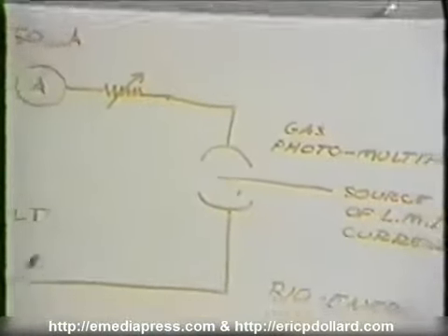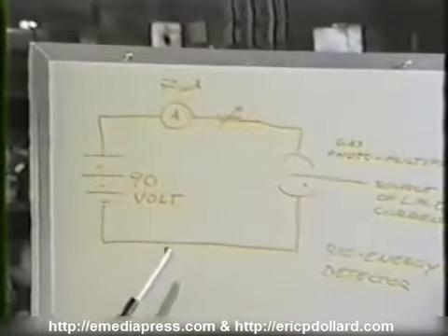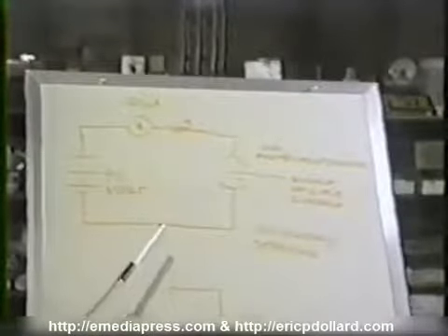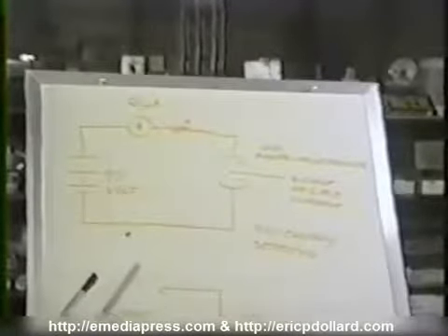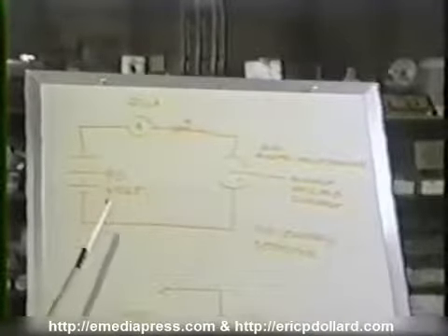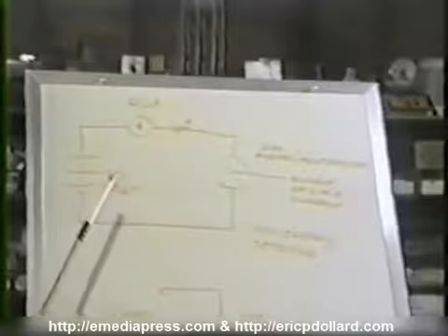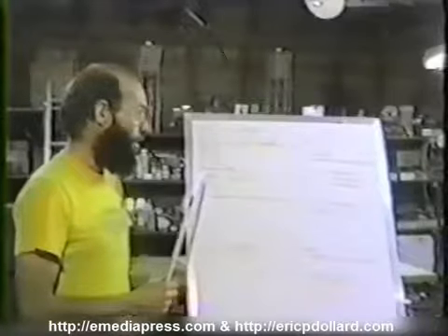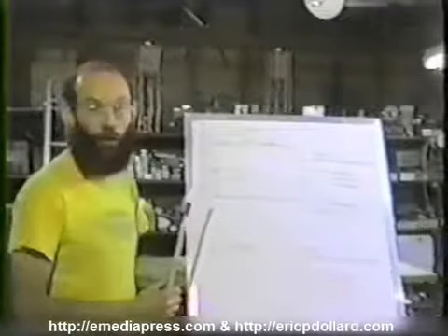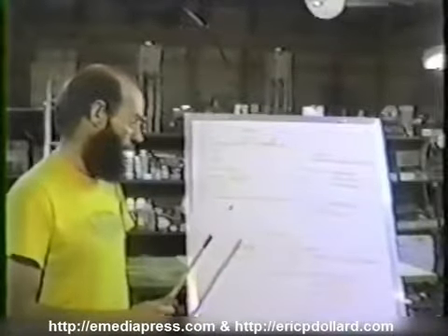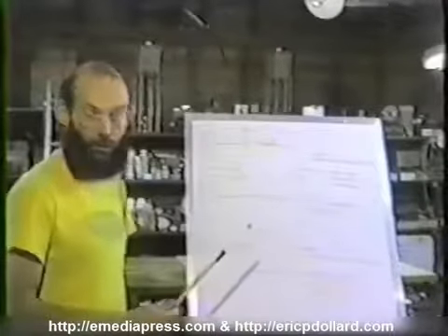The reason Farnsworth developed this tube was at the time the tetrode vacuum tube had not been developed yet. And being that Farnsworth was in the process of inventing television at that time, he needed very high gain, high impulse response, or you might say wide band amplifiers, and he just couldn't get that out of the old triodes. So he decided to abandon the hot cathode grid tube completely and came up with this photomultipactor tube, which now in its final form that's available to us today is known as the photomultiplier, which many people are familiar with and forms the heart of every television camera. Television camera tube, of course, being invented by Farnsworth, as many know.